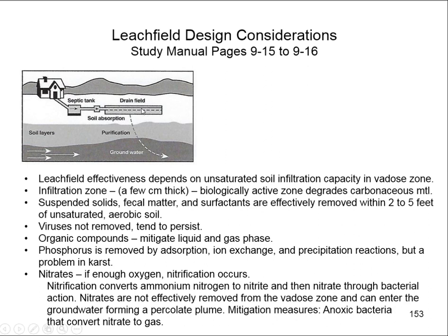So here's a little diagram showing you the drain field. And so it depends on the soil's ability to infiltrate and degrade the material we're putting in. So things like our fecal matter, surfactants are generally removed within 5 feet.